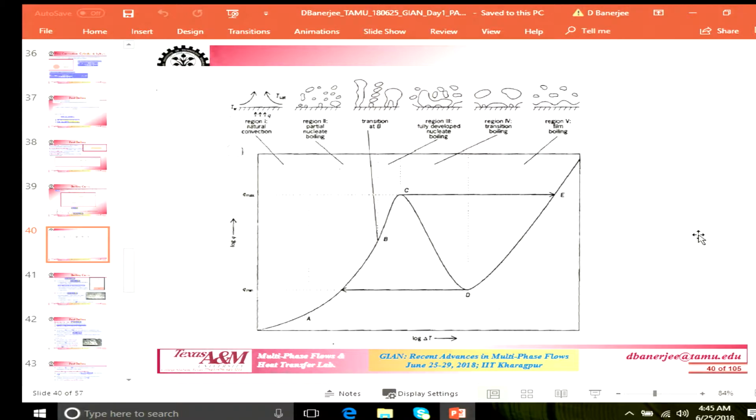Okay. The question is, what do you mean by surface? You mean surface roughness, right? But surface roughness is a double edged sword. The conventional measurements of surface roughness only measure the depth of the roughness. They do not measure the gradient of the roughness. You see what I am saying? I could have a lot of small sawtooths, or I could have a gradual rolling hill. Will both of them have the same roughness?